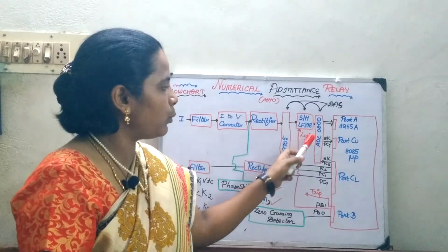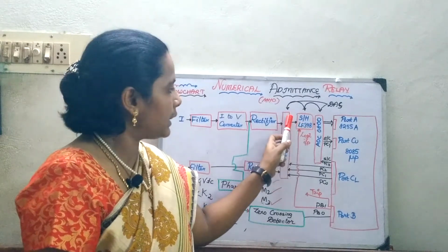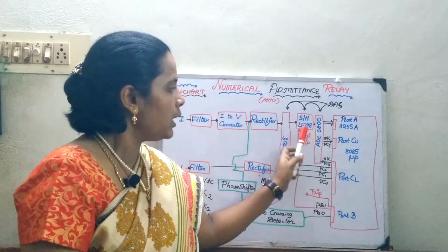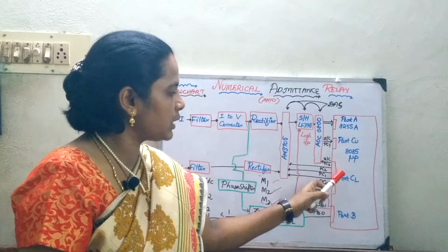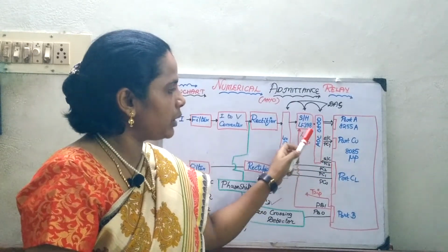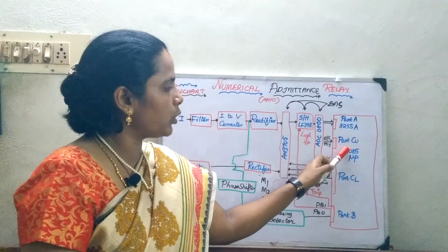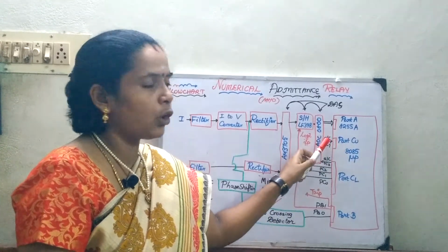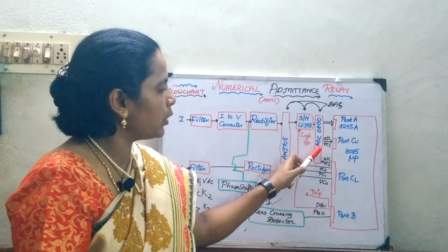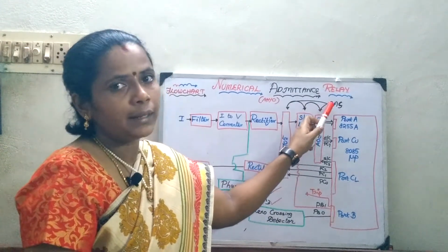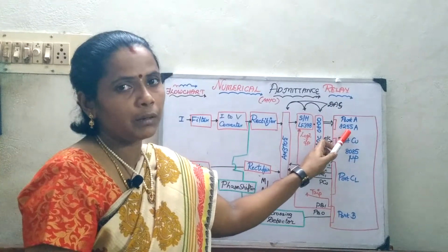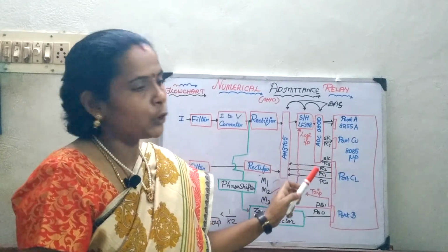Then the process of the sample and hold circuit will start, and this sends the data to your ADC, where the ADC, the analog to digital converter, does the start of conversion after receiving the signal from the microprocessor port C lower. Once all the data have been digitized, then it is going to be given to your port C upper by giving the signal of end of conversion. And the entire circuitry, the sample and hold circuit and your ADC, together is called your data acquisition system, and this system is going to be connected to the programmable peripheral interface to interface your microprocessor with it.